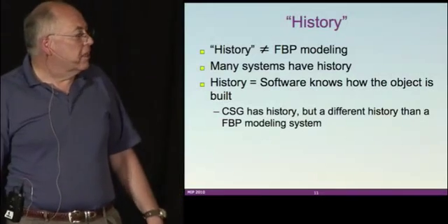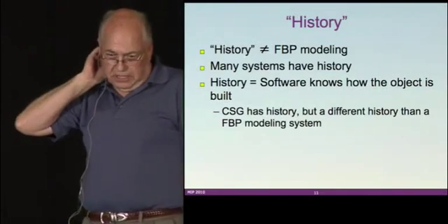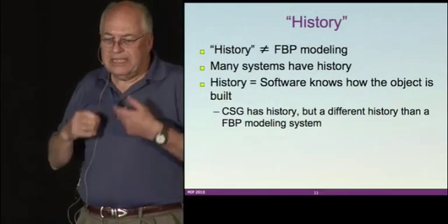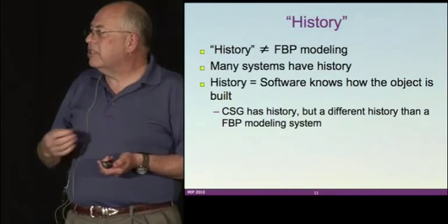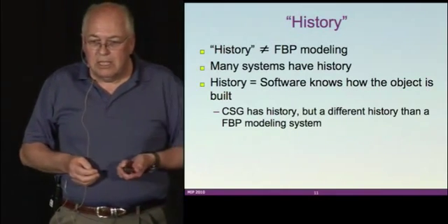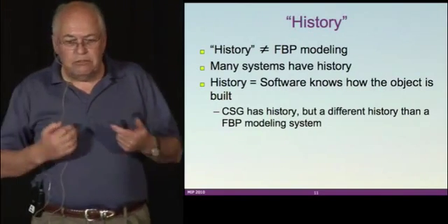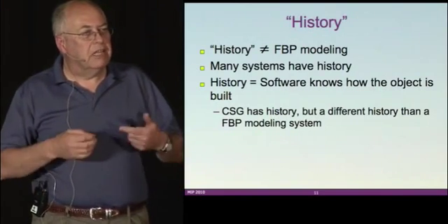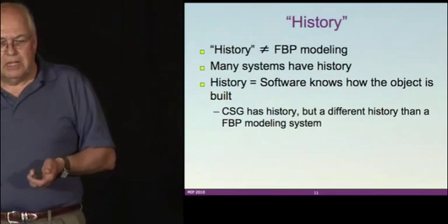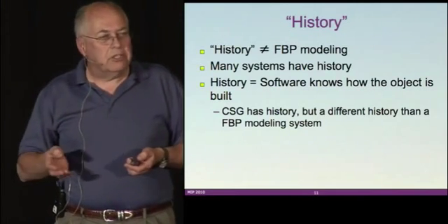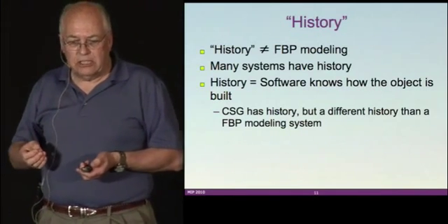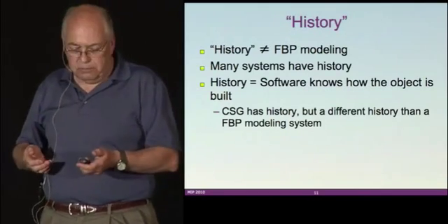Many of the analysts like to talk about history, so I'd like to say a few words about that. History is not the same thing as feature-based parametric modeling. Many types of systems have history. History means you know how you built it, and it relies on that. Constructive solid geometry, by the very name of it, has history. It's just different from feature-based modeling.